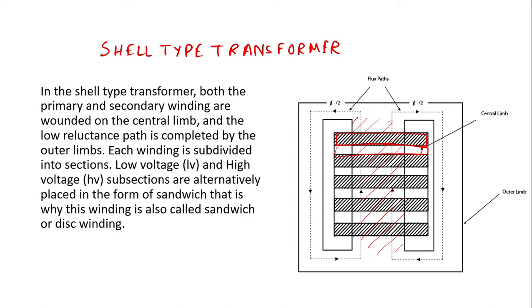And the advantage of a shell type transformer is that it has a pathway for its own flux to flow, which consists of the low voltage flux as well as the high voltage flux. So there are two limbs over which no coil is placed, and it gives a free pathway without production of any current through the coil.